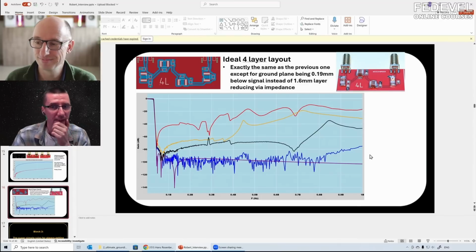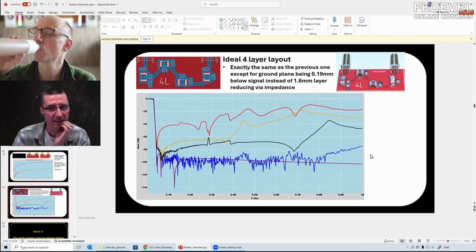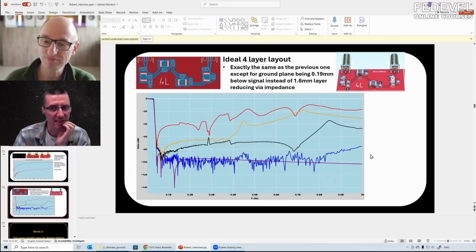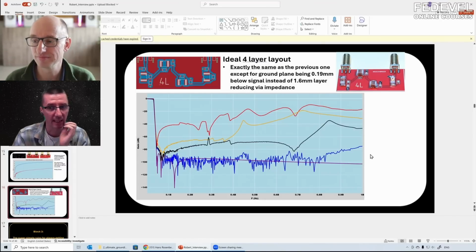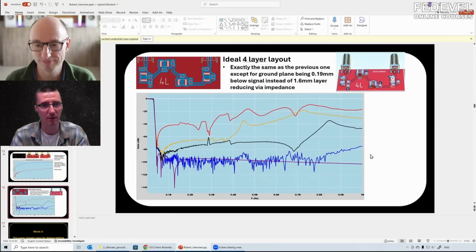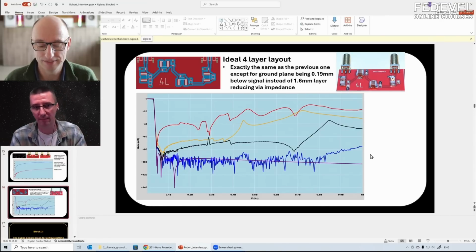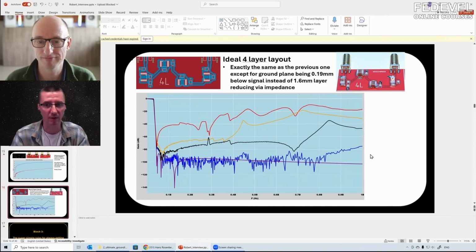And you know what I think is sometimes very sad, that many people insist on making 2-layer PCBs, and 4-layer PCBs are now cheap. Oh yes. There is absolutely no reason why people should use 2-layer PCBs, unless they manufacture millions, then yeah, you have to optimize. If you are making a prototype board for yourself, or if it's hundreds or even 1,000 or maybe 10,000 units, there is absolutely no problem. Go for 4-layer. No, exactly. In the last few years, prices have dropped so much, especially with the Chinese suppliers. It's amazing.